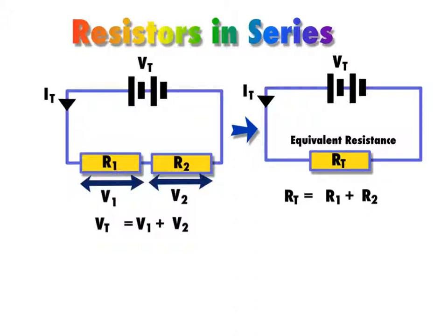And that follows the rule that the total voltage in the circuit here equals the sum of the voltages across any components on their way round the loop. So we have to drop, say, 12 volts here, we drop 6 of it here, and another 6 of it here, and we end up back at 0.